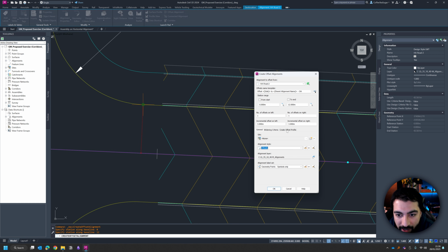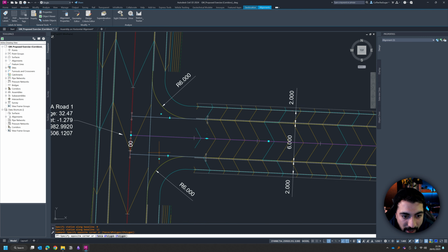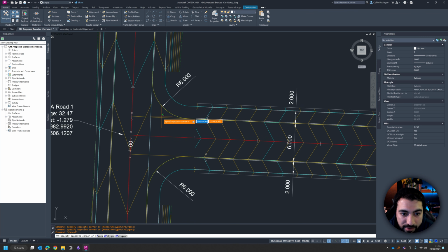I'm gonna hit OK. But before I hit OK, you can see which one is the parent profile, the vertical profile for road 2, and we can superimpose it on another profile, or we can use cross slope from parent profile, so it picks up the slope from the parent profile, and then it can name the alignment for you. So offset, and then these are the Civil 3D parameters. But in our case, you just make sure this is -2.5, and then hit OK. So now you can see these 2 new lines appeared, and they are your offset alignments.